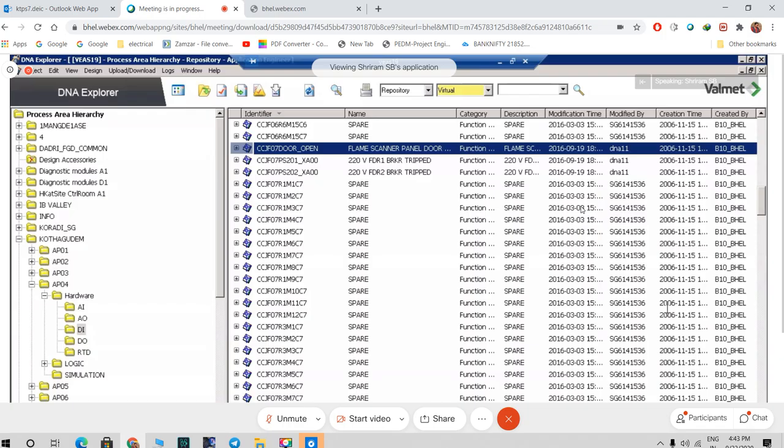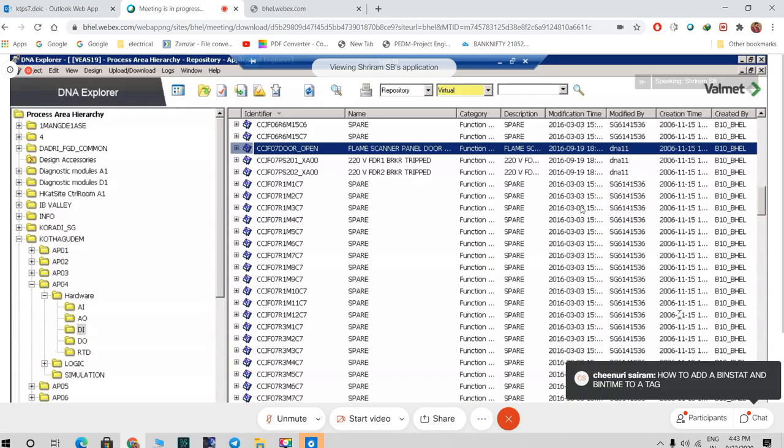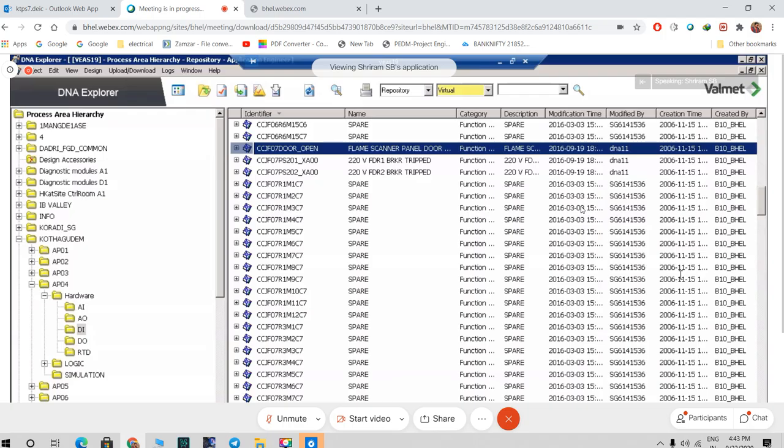Can the motor drive generate an off command a second time if it failed to stop at the first attempt? Usually, whatever commands are there, they are pulse times. So it will only operate for a maximum of say 10-15 seconds, or whatever is configured in the block. After that time, it will die and give an error that it failed to stop or failed to start, whatever may be the condition. If you have to give it a second time, then you have to acknowledge it and correct it on the field side. Basically, why it has failed to stop, you have to attend to first in the field. We call it a watchdog whenever this kind of alarm comes. Once that is rectified, the watchdog will get acknowledged, and then if you give another off command, it will take.